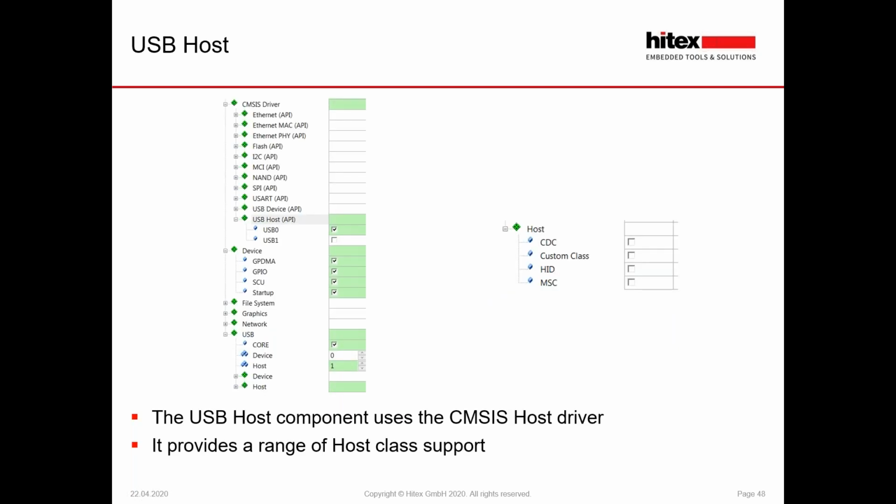So here again, we follow through a very similar setup. This time we're using host support, and then we can nominate what class we're going to use, and then the CMSIS driver. This time we're choosing the host driver, and we can select which peripheral we want to use.